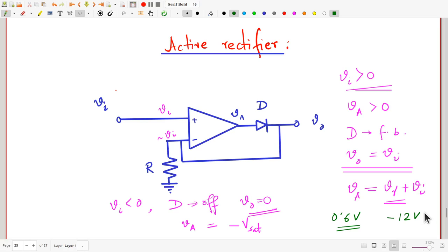Why? Simply because the op-amp cannot change its voltage at the rate at which the input dictates that it change. So it changes as fast as it can. Since it's limited by the slew rate, it changes at the slew rate. In fact, by feeding an op-amp a high enough frequency input voltage and looking at the output waveform using, say, a cathode ray oscilloscope or some such device, you can easily measure the slew rate.